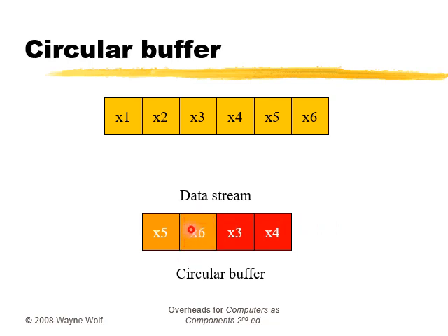We have x3. And next, if we want to throw out, what will be thrown out? x3, and x7 will come. However, we do not have x7, so we will not go further. So this is the circular buffer. We are just throwing out the old data and we are moving just the new data. So what are we actually doing? We are moving the head of the buffer in time. So that was about the circular buffer.